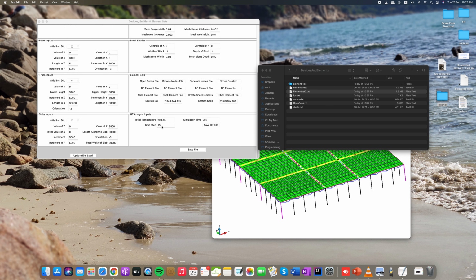So after structural analysis and heat transfer analysis, this temperature file will be created, so it knows which temperature data I need to put there. So once you have completed all these tasks, you just give how much the temperature simulation time is. Like my fire simulation, I take 20,000, and my steps, each step I take like 5 seconds.